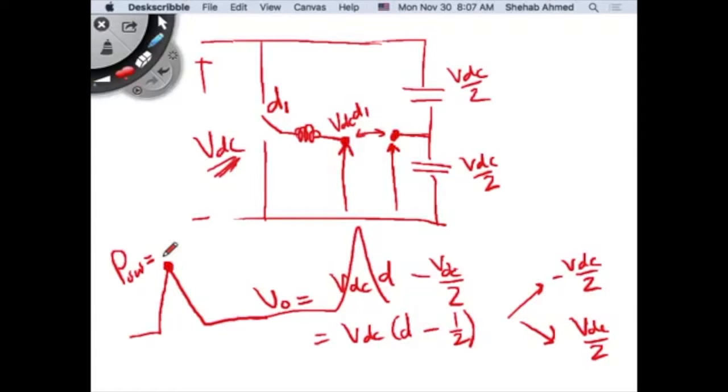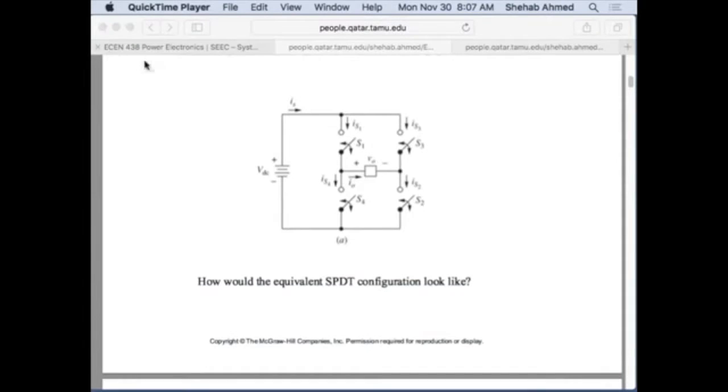And if you want to make it small, definitely go for something without a heatsink. So maybe in that case, definitely go towards a full bridge, right? It depends on how you optimize what the load's requirements are and how the system is optimized, what the ambient temperature is, etc., to be able to choose. But these are 2 topologies that we can utilize to produce AC voltage here.